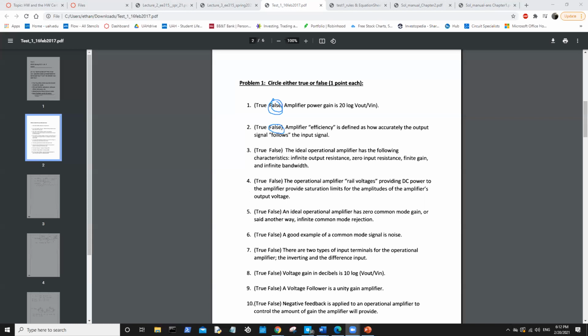Yeah, so other Ethan posted in the chat. So from Google, operational amplifier, the ideal op amp is an amplifier with infinite input. So look at this, we can immediately say, oof, false. But infinite input, infinite open loop gain, 0 output resistance, infinite bandwidth, and 0 noise. Noise isn't addressed here, but we can already tell that this is false simply because it has 0 input resistance when we want infinite input resistance.